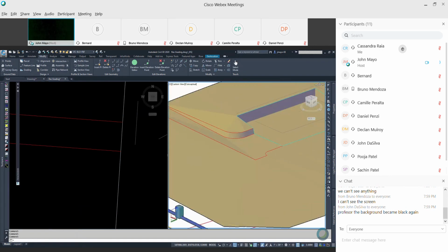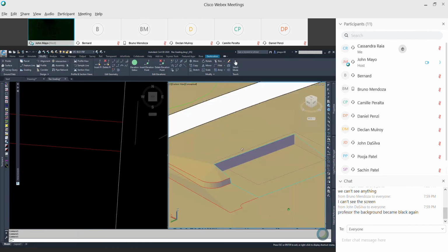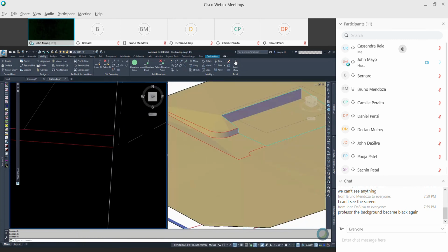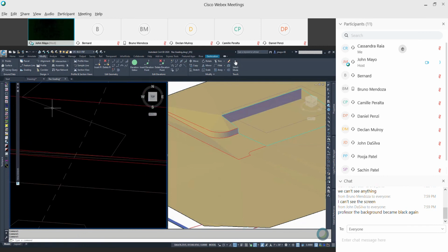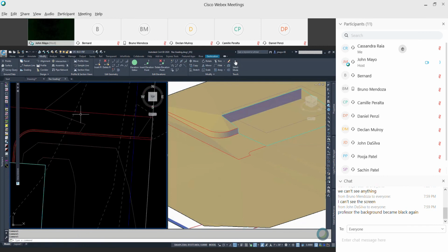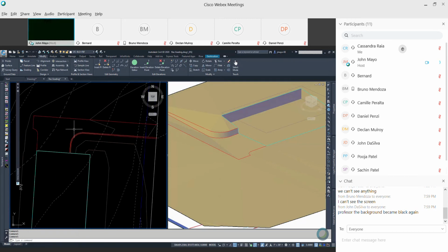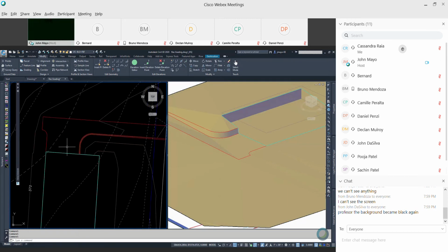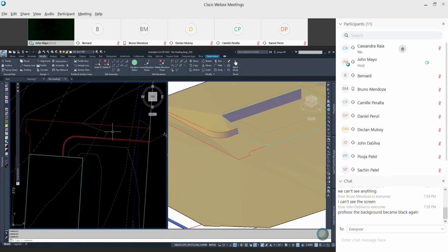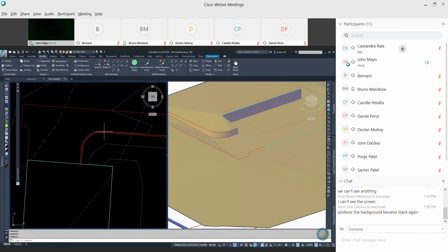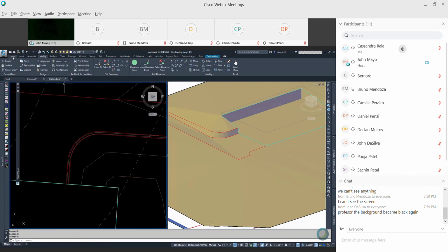All right, so the last thing I want to fix is that my driveway is not really level. And we can see that because my contour should be going straight across if it was level. I want to maintain my cross slope away from the building here, but I have enough slope here to send water to the driveway, and I'll have enough slope either up or down to get the water off to that corner and away from the building. So what I'm going to do is I'm going to draw a feature line.